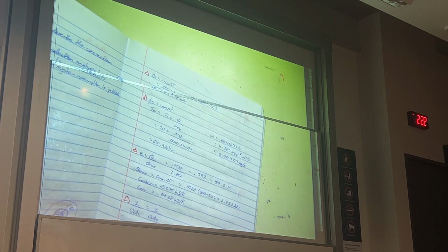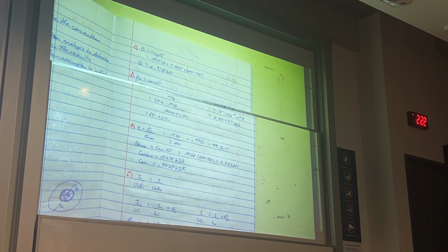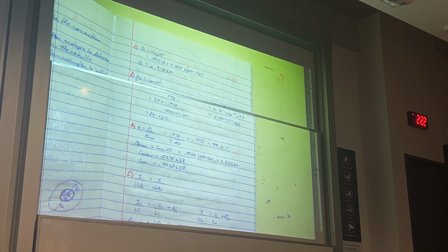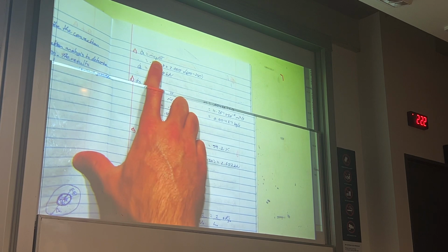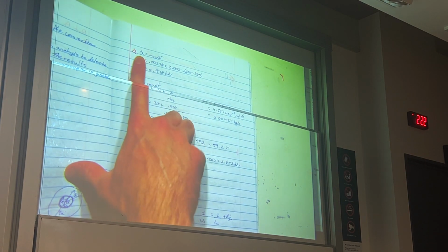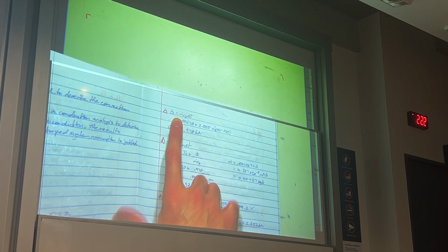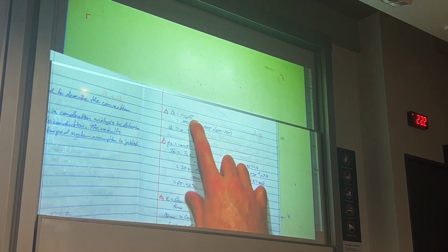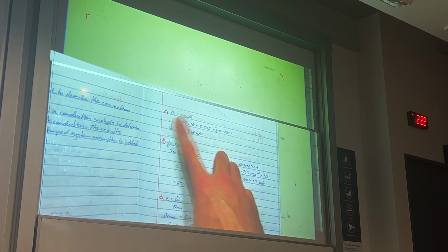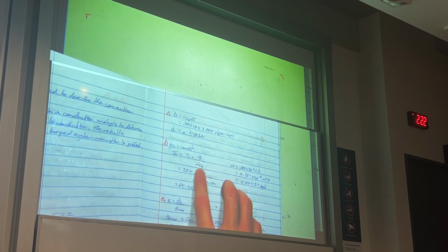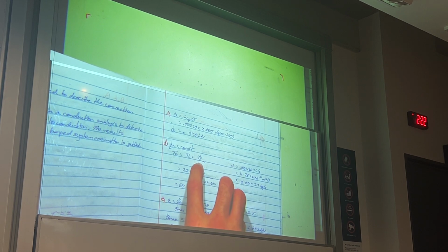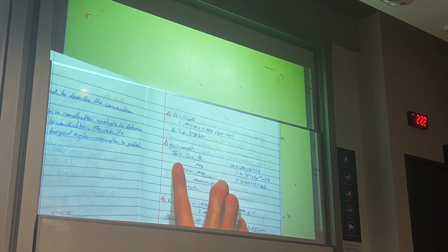Anyway, we know that our exit temp is going to be our inner temp plus something, and then we take this energy balance up here. Pretty much what I've done is I've taken this energy balance up here, because I know it'll be the same for the water. I've expanded out this temperature term to have T exit minus T inner, and all I've done is I've rearranged for T exit. So you can see we divide Q dot by m c_p, gives us that term, and then we take our T inner across to the other side, and we get our exit temp here.